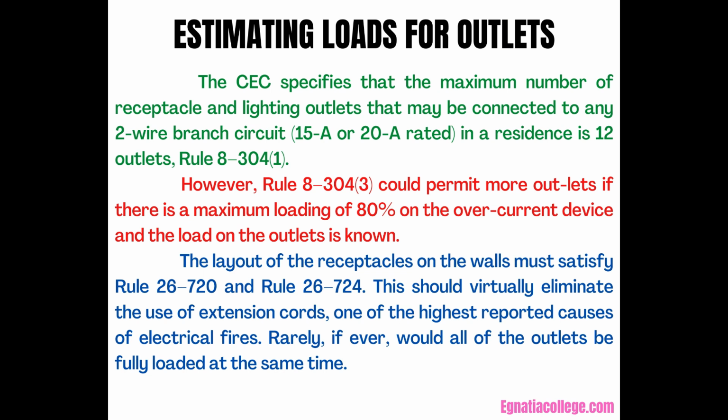The layout of the receptacles on the walls must satisfy Rule 26-720 and Rule 26-724. This should virtually eliminate the use of extension cords, one of the highest reported causes of electrical fires. Rarely, if ever, would all of the outlets be fully loaded at the same time.